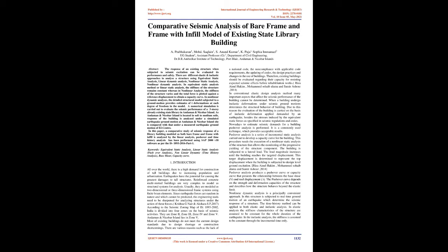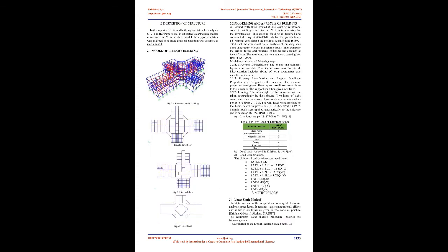In this paper, a comparative study of the seismic response of a library building modeled as both bare frame and frame with infill is carried out. Linear analysis, pushover, and time history analysis have been performed using SAP2000 V18 software as per IS 1893-2016 Part 1. Keywords: equivalent static analysis, linear static analysis, pushover analysis, nonlinear dynamic, time history analysis, base shear, capacity curve.